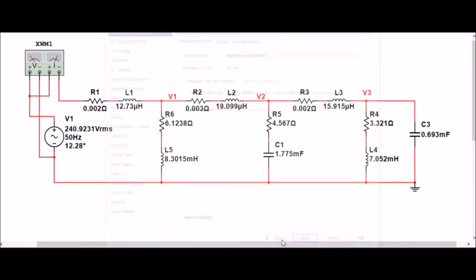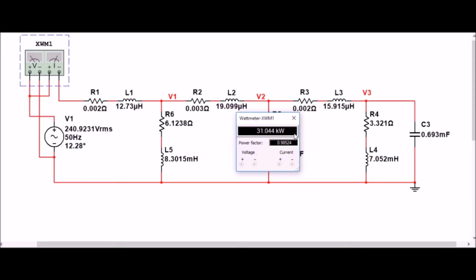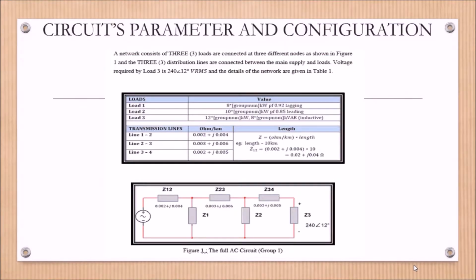As you can see, the value of power factor is 0.98, similar with the requested value by the question. This shows that capacitor improved the power factor. First of all, we look at the circuit's parameter and configuration,